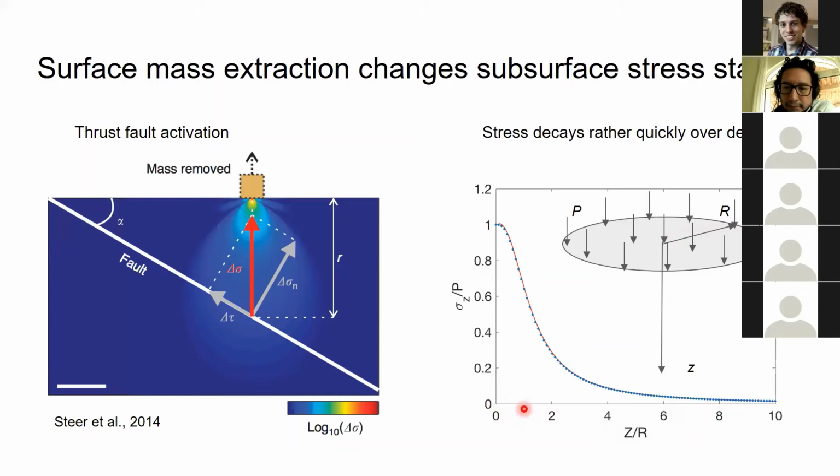If the depth is 3 times the radius, around here, the vertical stress is already below 20% of the regional pressure. And more complicated surface loading can be constructed using superposition of these many point forces on the surface. This is what we did for the quarry and also the quarries near the Cruas power plant. The next slide.